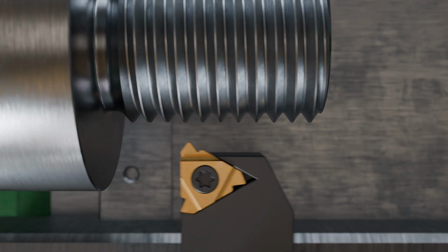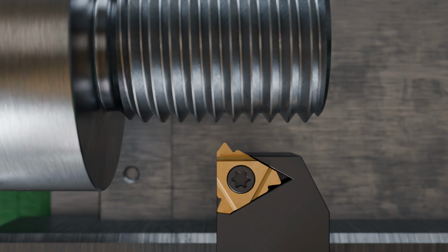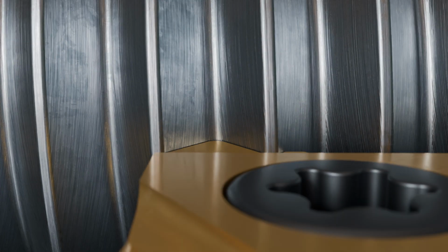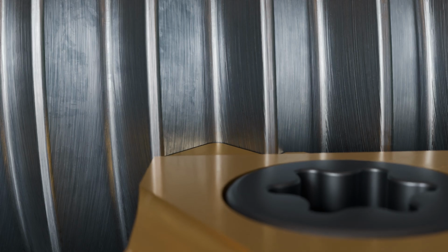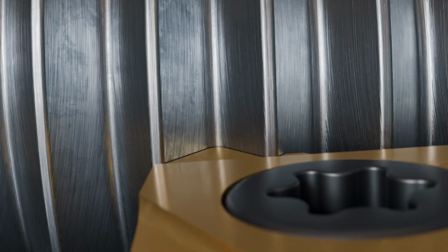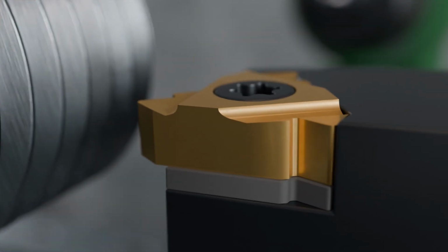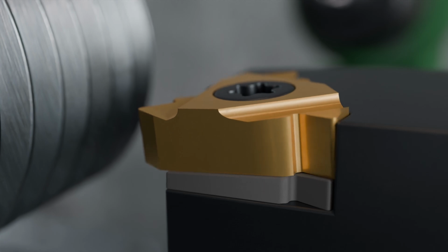To create a symmetrical clearance angle on the thread flanks, called the flank clearance angle, and to ensure a correct thread profile, the insert must be tilted according to the thread's lead angle. To achieve this axial tilt of the insert, there are specially inclined spacers for each thread type, called shimming plates, which are placed between the tool holder and the insert. Additionally, these shimming plates are tilted downward by about 10 to 15 degrees in the radial direction to provide a clearance angle in the radial direction.